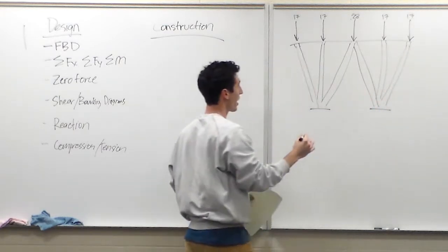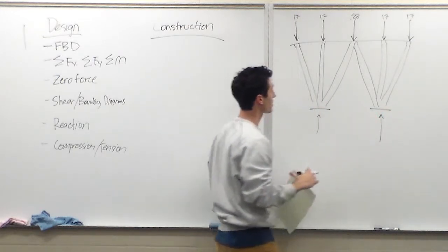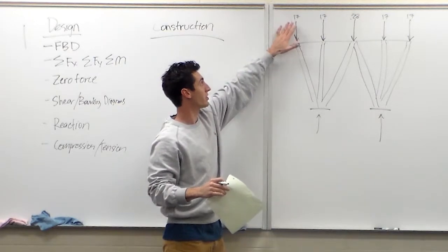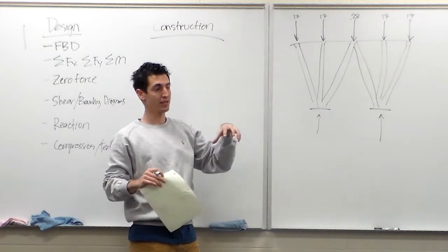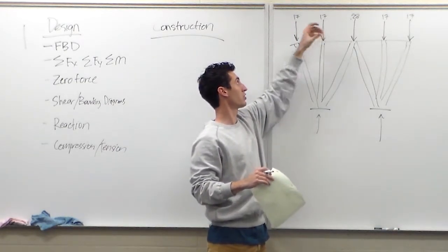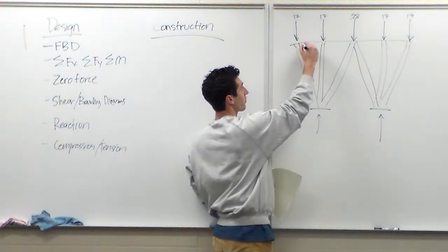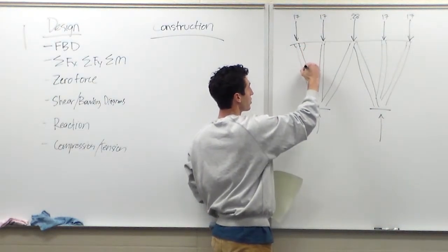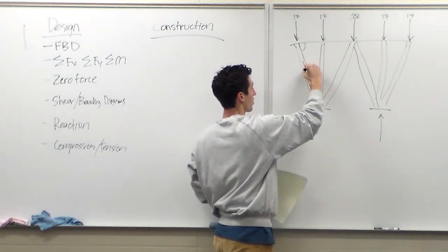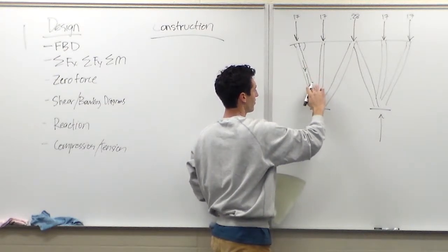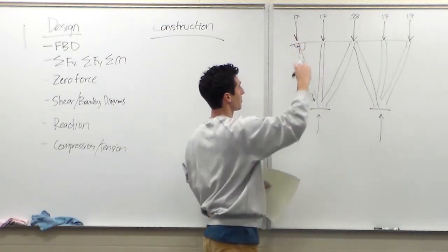Okay, and then we have reaction forces. So there are 2 ways that you can solve for these 2 reaction forces. You can make these loads percentages out of 100, or you could set your goal weight and then figure out based on the percentages the actual load in pounds that will be coming down. Then once you solve for the angles, you can actually determine the compression. Oops, I do those backwards. Backwards again. You can solve for the compression here inside of these beams.